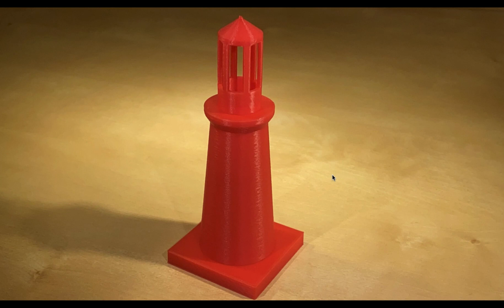So here a nicely resolved shot of our Lighthouse. So you see all the features came out pretty nicely. It was able to go out here, make an overhang. Remember, the important part here was that the angle should be 50 degrees or steeper. It also fairly successfully did this cage here, and I'm actually surprised how well this came out, but I guess it's a good printer. So overall, a pretty successful 3D print.